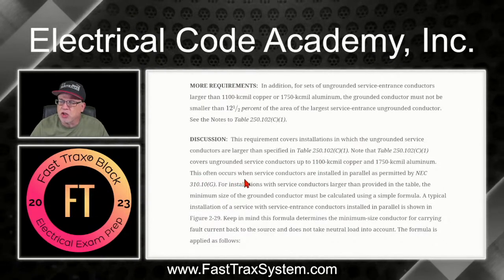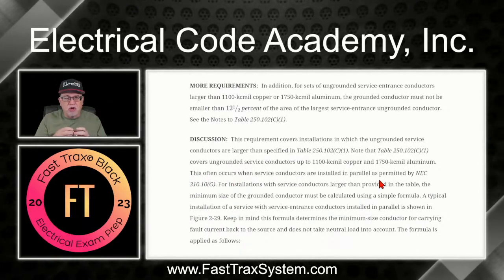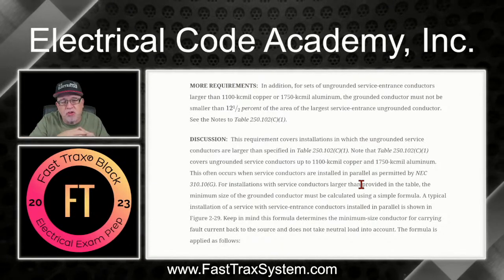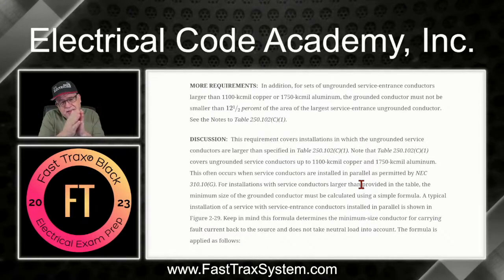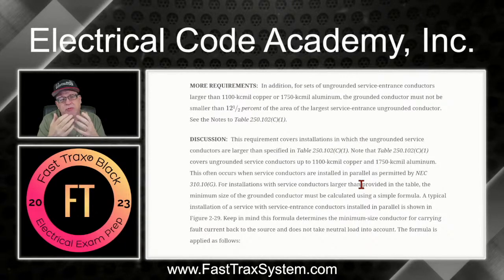This often occurs when service conductors are installed in parallel because you're trying to get more amps, so you want smaller conductors to run, and you break them out into parallel sets. That way you get to use the ampacity from each conductor acting together. So if you had two parallels of, let's say, 500s that were 380 a piece, then you add them together in parallel, and you get 380 times 2. That's what you're trying to do. That's why we parallel, right?